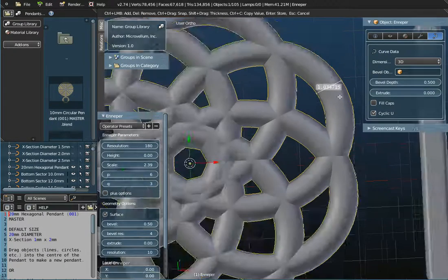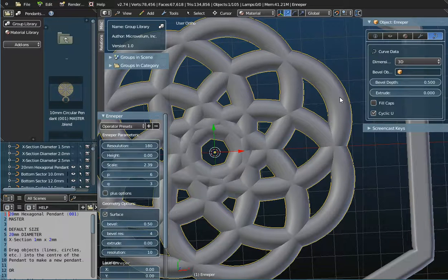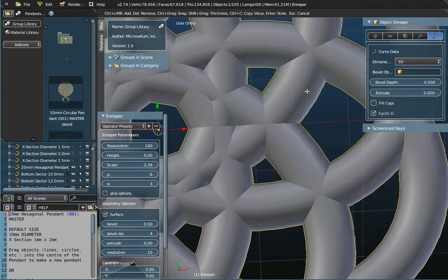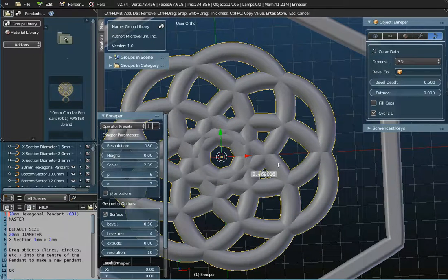Now you don't really want to be going much lower than that. I mean, you can, especially if you've got a really fancy 3D printer, but in general terms, if you're printing at somebody like Shapeways, you want to stick to something like 1mm, which is why this value has been set for you. Now, in terms of fine detail that can be printed, you can't see a hole that's much below 0.5 millimeter, so you would be able to still see that hole if you 3D printed it. If I just press the escape key to come out of that.